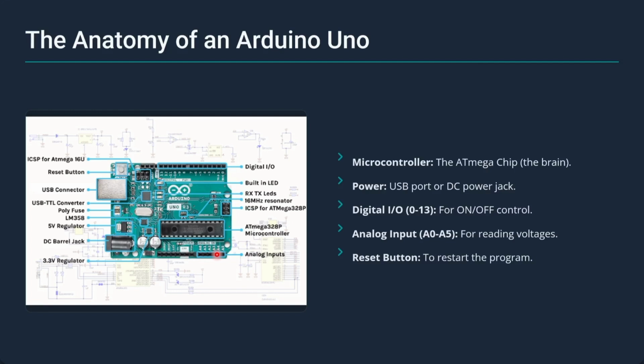For example, the MQ3 sensor works on analog because it senses a value, and it works based upon that value. So whatever analog signals we get, we need to connect to these pins. Digital input and output just does low and high, on or off. For sensors that need to work based upon some value, we use the analog input.